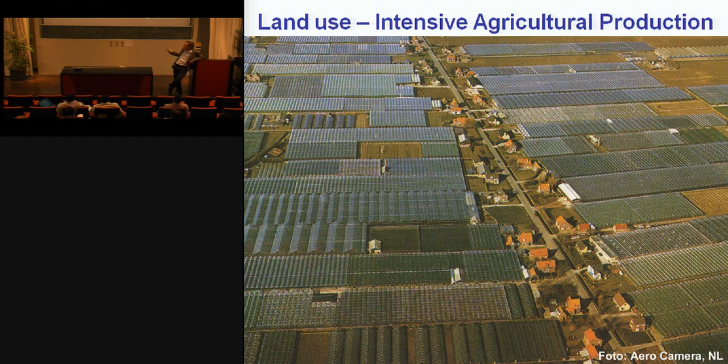So you make the surface very impervious and produce a lot of direct runoff, but not a lot of soil water storage, infiltration, percolation to the groundwater, and all that. So we produce more direct runoff with these types of structures, and therefore less evaporation. But the efficiency, because of the change in the energy balance of these systems, can be very nice. So you can produce more tomatoes per hectare and higher yields just because of the controlled climatic conditions.